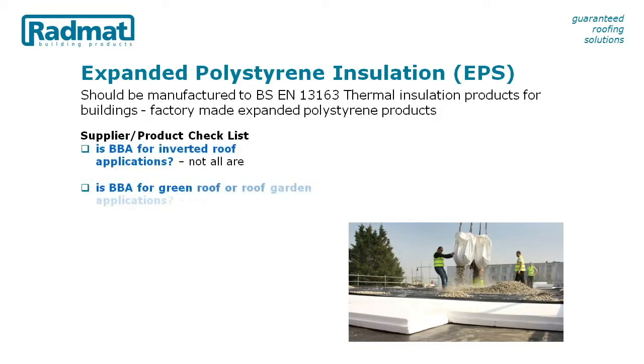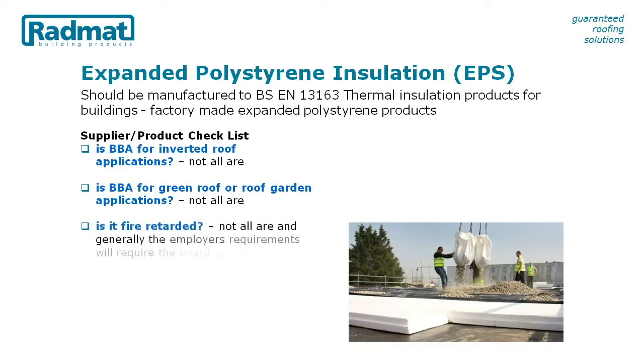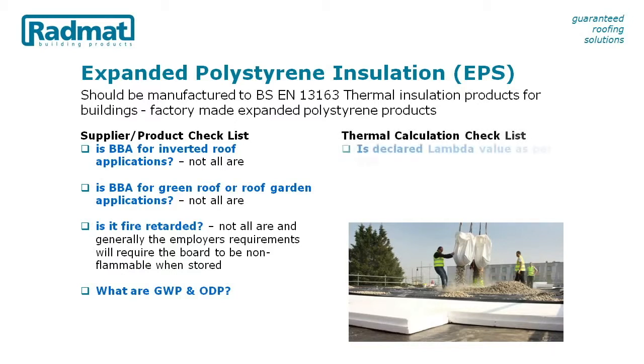Is it BBA certified for inverted roof applications? Not all are. Is it BBA certified for green roof or roof garden applications? Not all are. Is it fire retarded? Not all are, and generally the employer's requirements will require the board to be non-flammable when stored. What are GWP and ODP?